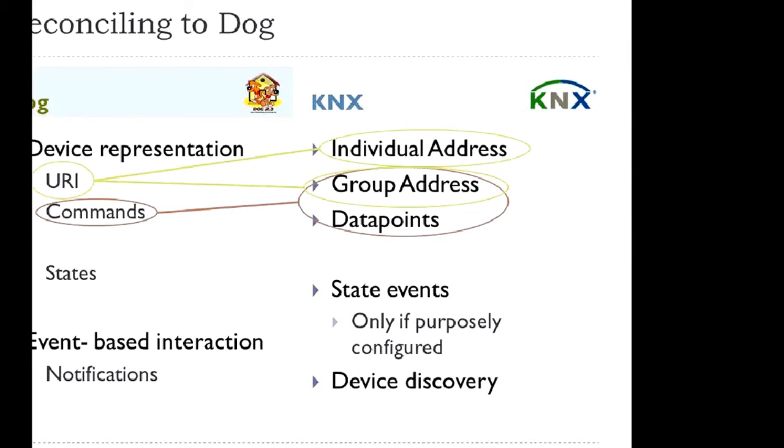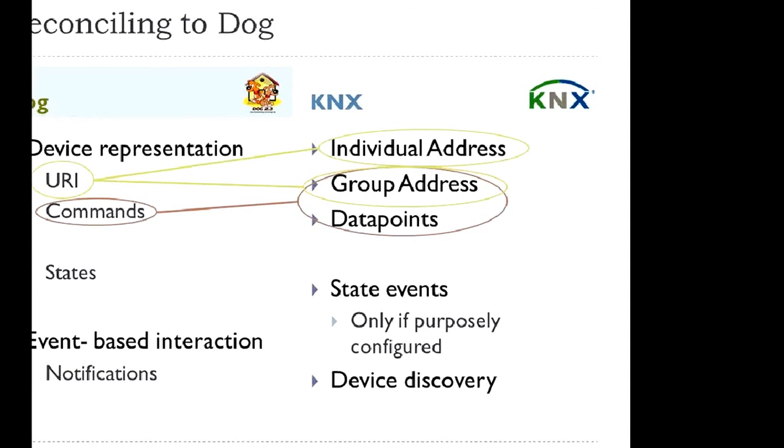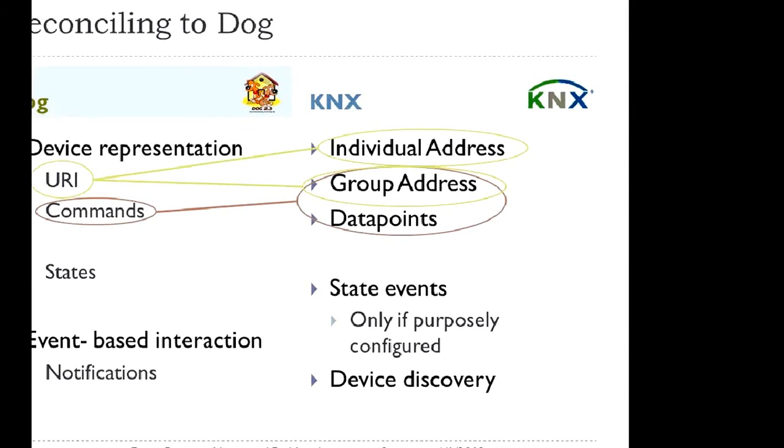Okay, and these are defined in the network. So if you try to open the network driver of KNX and the on-off driver, you will see at some point some indication saying DPT switch or DPT, I don't know, something else. These are the standard data points used. So the drivers are establishing this association.